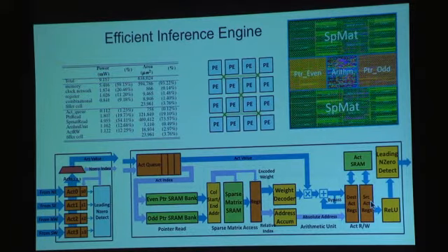So we basically, in a distributed manner, find the non-zeros in the input activation and broadcast those to all of these tiles. Every tile multiplies that activation by its portion of the column that's non-zero, basically using the sparse matrix representation to skip over the zeros without having to visit them, and then updating those. And then you switch the input and output activations for the next layer.